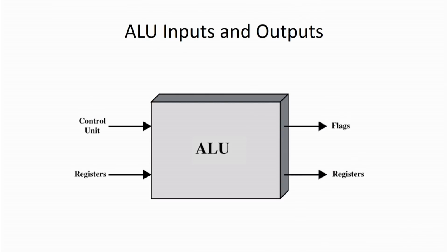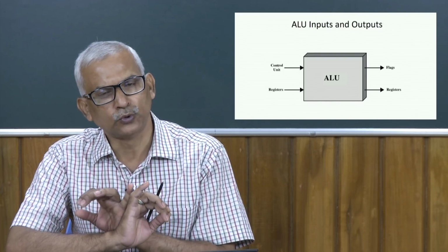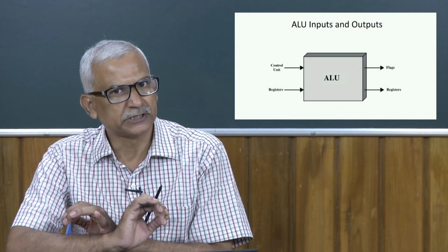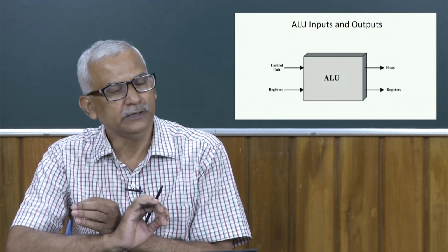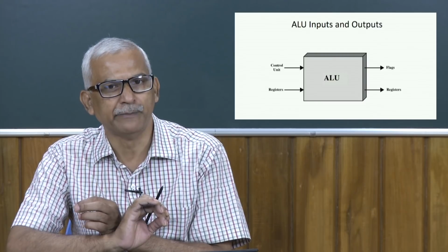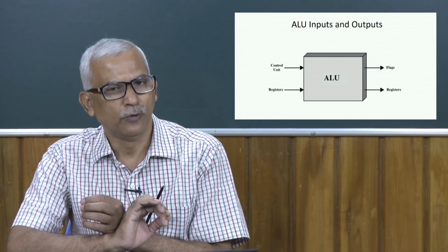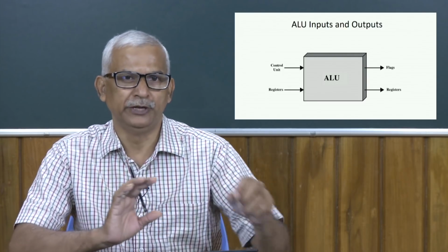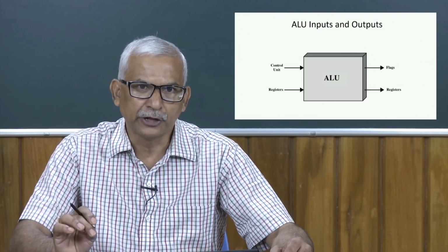So, these are the registers. What registers are we getting? Basically storage elements. One, we have the general purpose registers. Secondly, we may have some dedicated registers to store only data and only addresses. Then we have some special purpose registers. Here I have mentioned four registers called program counter, instruction register, memory address register and memory buffer register. Along with that we have a special register called the condition code register, where we store the status of the processor. So, these are the storage elements we have inside the processor, and these are known as our registers.